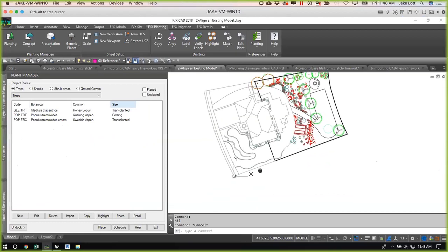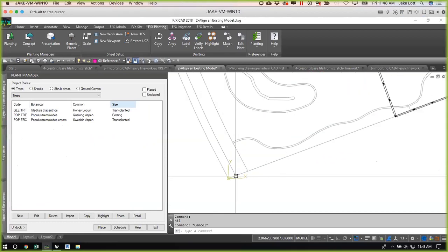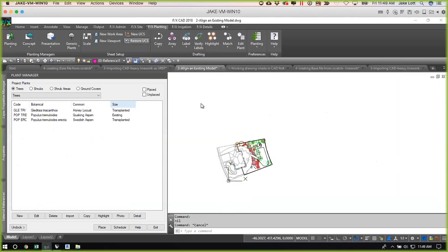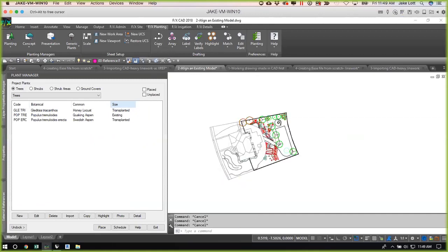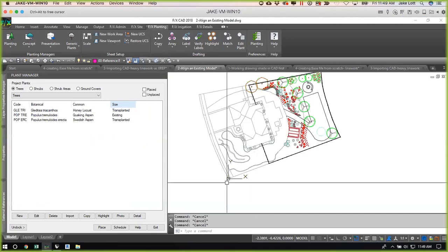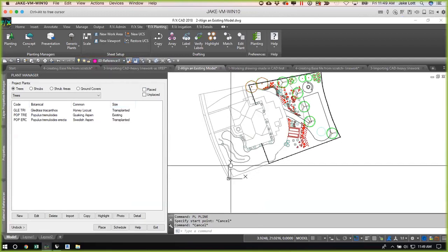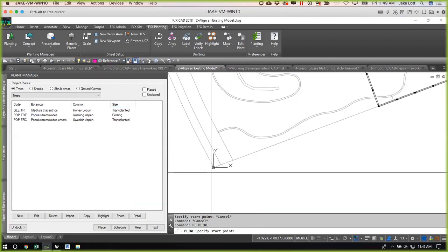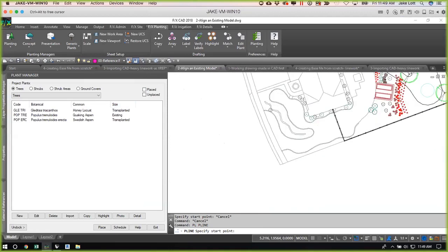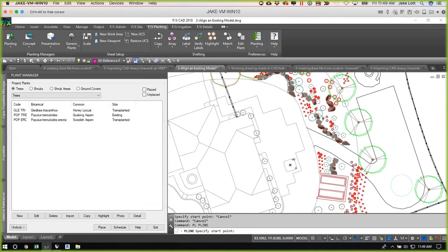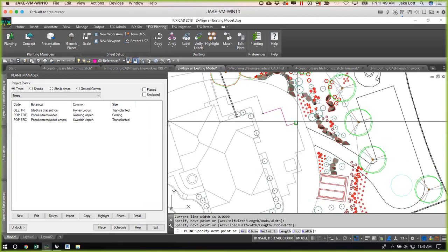Again, understanding where that insertion point is going to be the best way. But what you can also do is essentially, and let's just make sure I don't have anything there, cool. I can actually place on a layer. So I'm going to create a layer. I called it just my reference point, and I'm just going to create just a spot on this plan somewhere that I know exists in that other one. So maybe it's this right here. We're just going to go ahead and just trace this real quick as kind of that reference point.